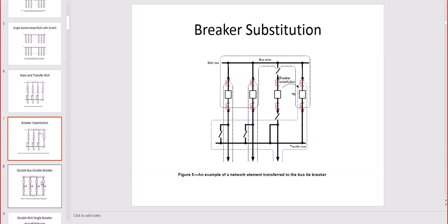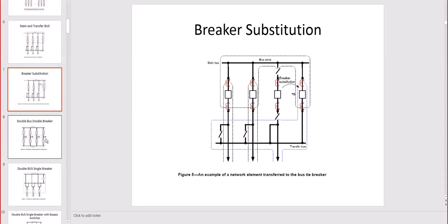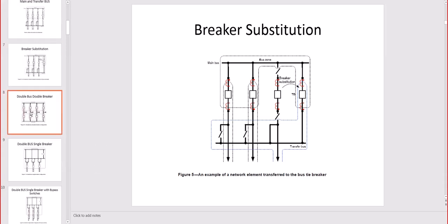It is a dynamic change. That's why in the new relays you can do that very easily. You have logic in the new relays that can consider these transfers, so you know when the breaker is out of service, and you can even have different settings, as we're going to see. It's called dynamic settings.